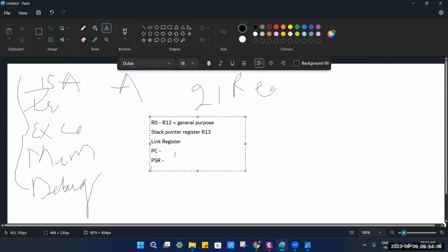Similar to that, there is also a control register, in which the control bits, like privilege modes and stack selection, are kept. Both these registers are not accessible to be written; they are read-only. You can only read them, you cannot write them. I was asked in an interview about a practical use case where I can declare a static const volatile pointer. I said PSR and the control register. I suppose my answer was right. Correct, the answer is right.